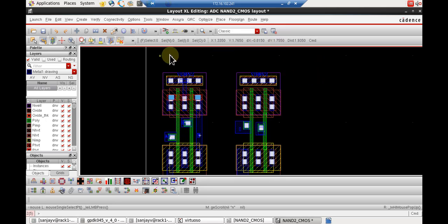So I need to make a VDD. From this, I make a metal layer out here. So I have connected this to the VDD out here. So this has become a VDD, and now both of them are in parallel. So I can connect a wire out here and bring it here. So I connect these two, and now these two also, since they are in parallel. Here I have given VDD, but these two have to be interconnected.